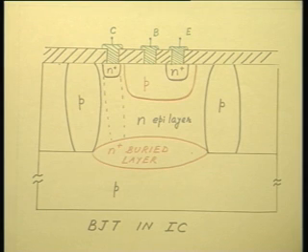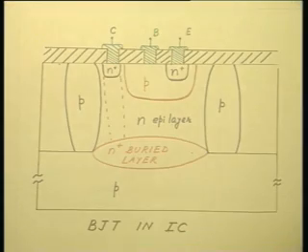So, since your p-type diffusion has a considerable depth, that means it extends in both ways as well. So, even if your original isolation window was small, there will be considerable spread on both sides, and therefore, you will have larger area requirement. Okay? That is one drawback. The other drawback is, of course, you see this junction isolation is p-type,